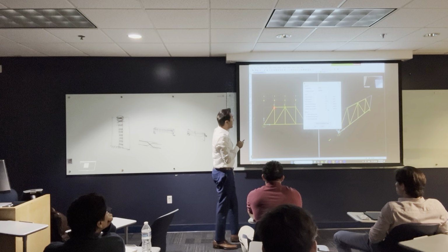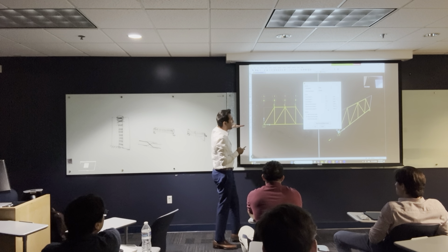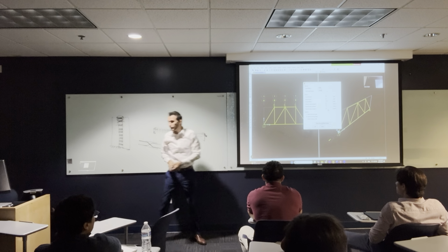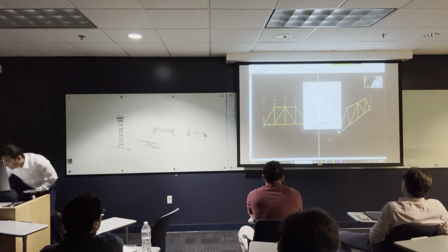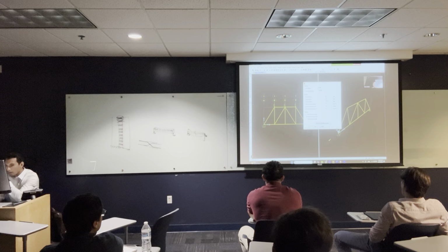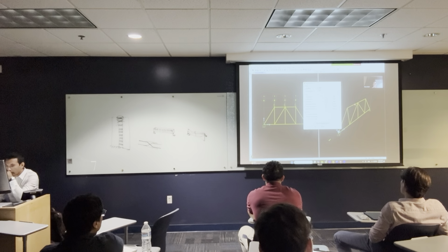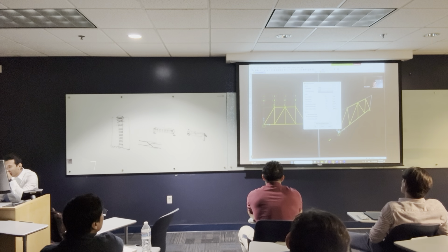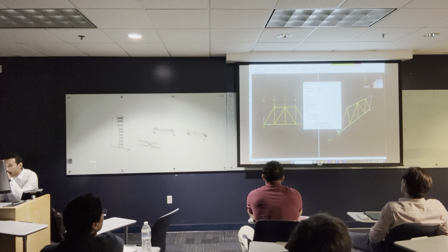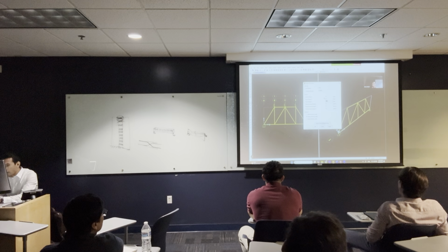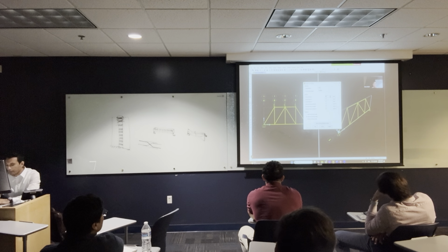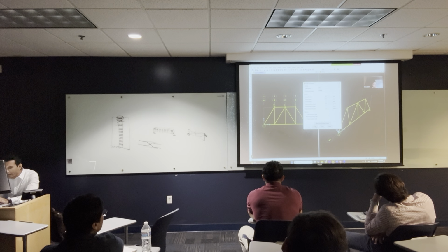We have a live load here, and it's going in the X direction. So I can exchange this from dead to live. Let's check the value of the live load. It's 5 ton. So I'm going to select this point, and I'm going to change this to live load. And where should I put it here? First, I have to make this 0. And is it positive or negative? Positive. I'm going to make it 5, and I'm going to hit OK.